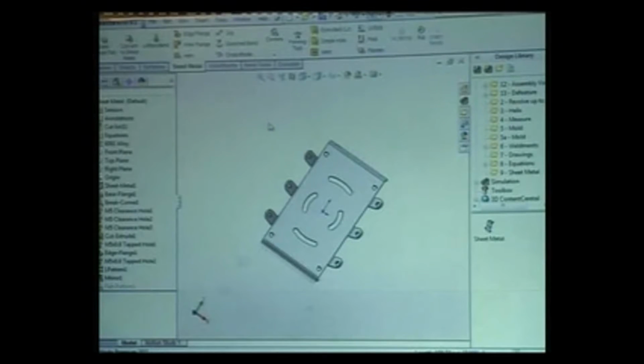Inside SolidWorks, we have various tools to define the bend calculations, which can be done by making use of either the K factor or the bend allowance, bend deduction. But now in 2011, we have introduced something called bend calculation, which is mostly required for varied bend angles. Let's take a look into this. This is the table I was mentioning. So this is how it looks.